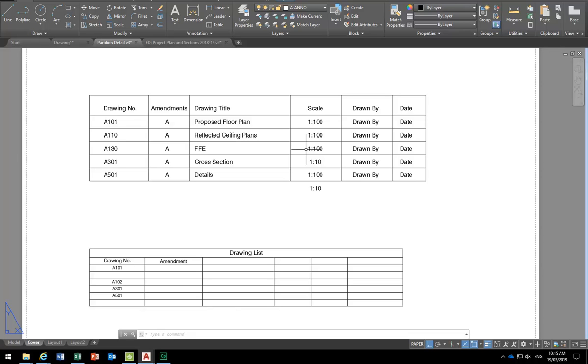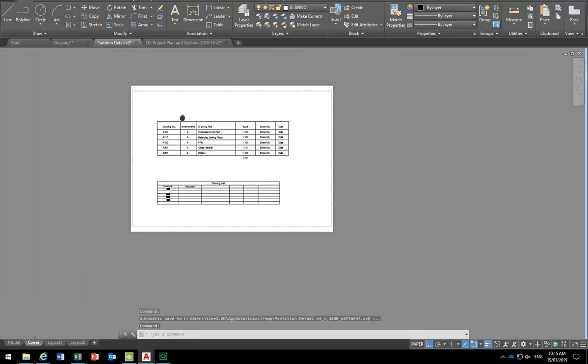I did one building that's almost twice that floor footprint on A3 sheets, and we were doing all the A3s at 1 to 200, and that located all the detail plans, and we'd have most of them in call-outs at 1 to 50 or 1 to 100. So that's it.